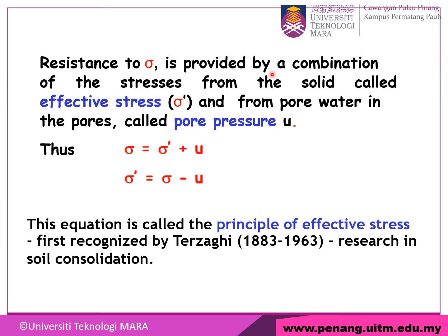Resistance to stress is provided by a combination of stresses from the solid, called effective stress, and pore water pressure in the pores. Thus, total stress is equal to effective stress plus U. Effective stress is equal to total stress minus U. This equation is called the principle of effective stress, recognized by Terzaghi.